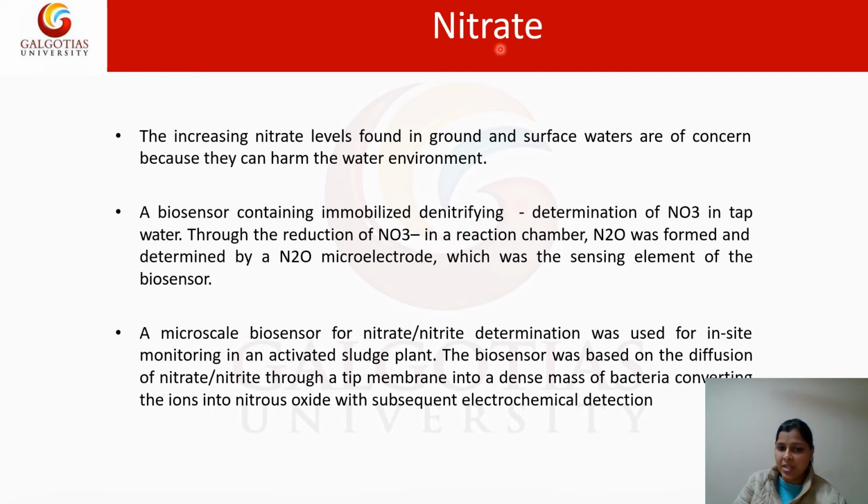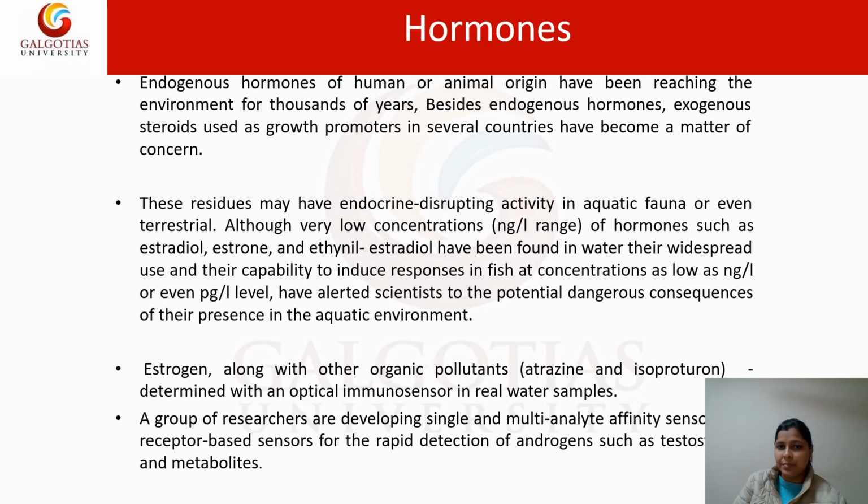Microscale biosensors are used for nitrate determination, and for in-situ monitoring in an activated sludge plant. The biosensor is based on the diffusion of nitrate through the tip membrane into a dense mass of bacteria, converting the ions into nitrous oxide with subsequent electrochemical detection.